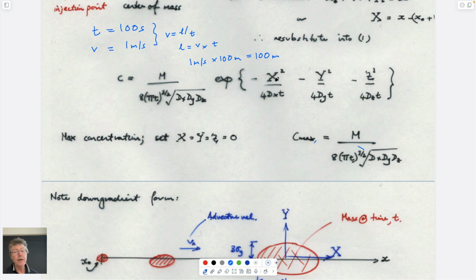So it's useful to do that because if we do use these migrating coordinates, it turns out that we can calculate what the maximum concentration in the middle of the plume is just a function of the total mass that was put in at time 0, which is conserved. At time 0 or at time 10 minutes or 100 years, it's still the same mass that's in the plume. And then just divided through by time.